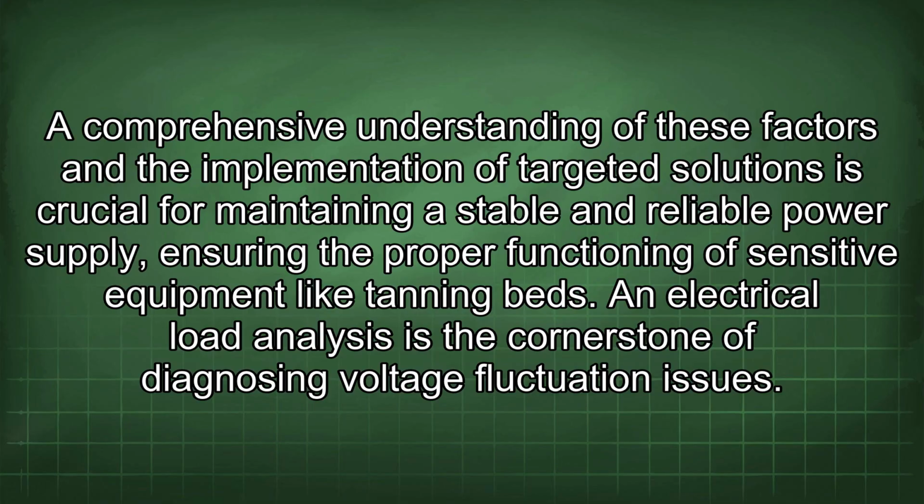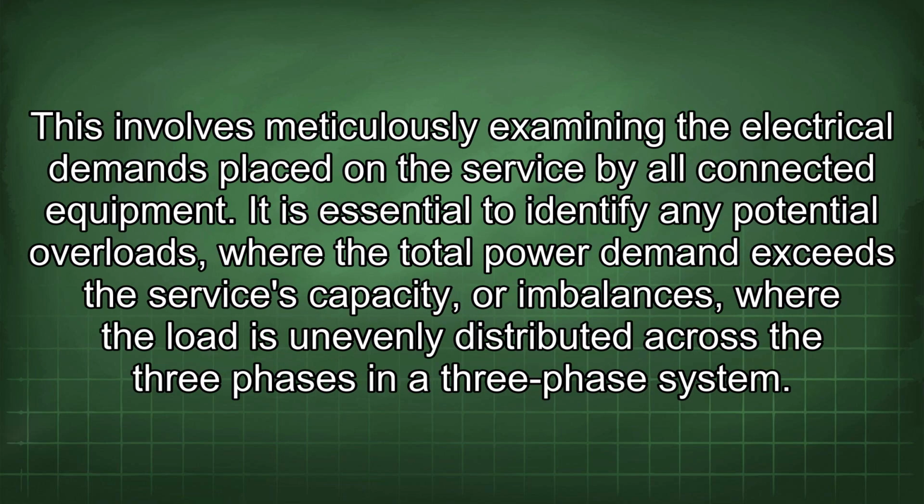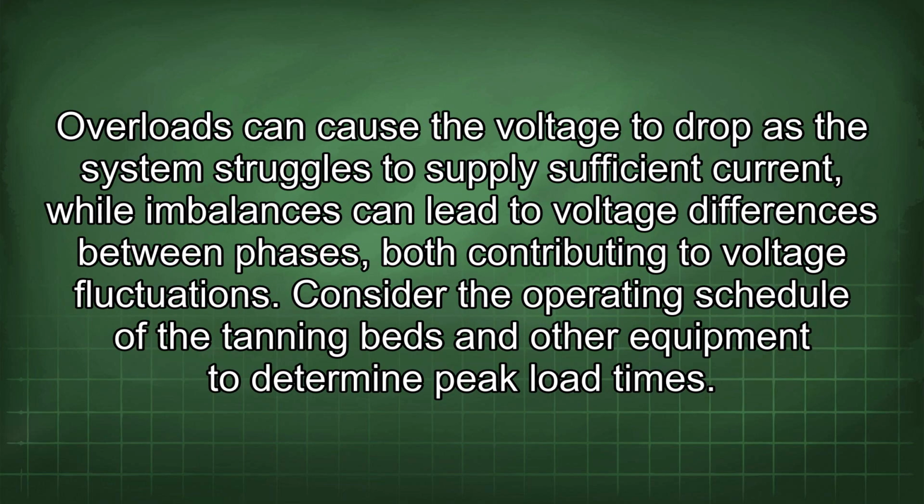An electrical load analysis is the cornerstone of diagnosing voltage fluctuation issues. This involves meticulously examining the electrical demands placed on the service by all connected equipment. It is essential to identify any potential overloads, where the total power demand exceeds the service's capacity, or imbalances, where the load is unevenly distributed across the three phases in a three-phase system. Overloads can cause the voltage to drop as the system struggles to supply sufficient current, while imbalances can lead to voltage differences between phases, both contributing to voltage fluctuations.